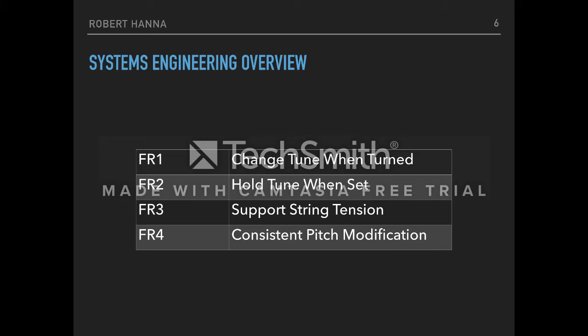Depending on the guitar and the gauge of the string, you can get some pretty high tension, so we definitely don't want it to break. Number four, consistent pitch modification. When you're relying on friction so much and on a 1-to-1 gear ratio, you are changing the pitch a lot per turn. And when you're wrapping the string around itself, the diameter is changing. So you can run into the case, it's not a huge deal, but it is noticeable at times. You don't want every turn to be very different than the last turn. So if I'm turning 5 degrees and it changes the pitch 10 cents, you want the next 5 degrees to change the pitch 10 cents, if that makes sense.